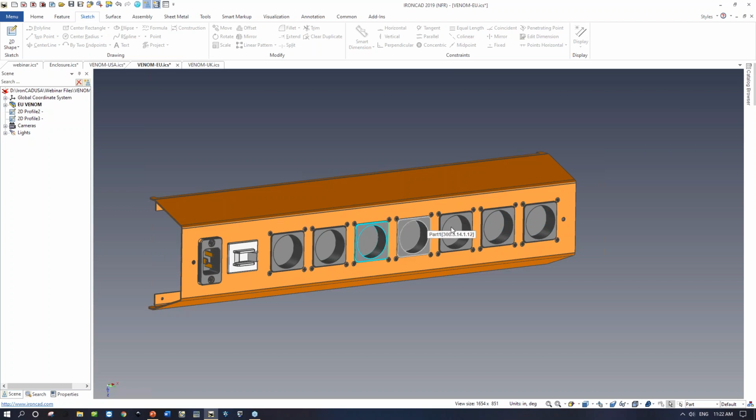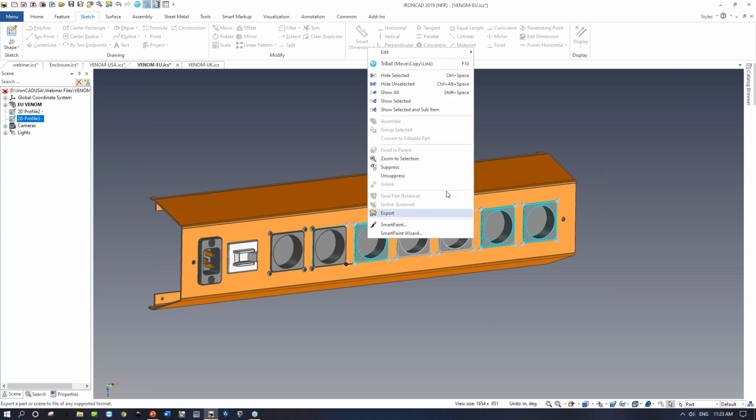Hey, RJ, do you know a simple way to do this, or am I doing it the right way? Would you do it just like this? He might be on mute. You can use box select. Really? Just on those parts? Yeah. I don't want the outside parts, though. You can use the box select down there on the bottom right. Next to the part selector down at the bottom, there's a box select command. Just use that. Oh, really? Ah, and then I could use Shift Select to get rid of what I don't want, right? You know what? I don't even need to do that. I like what you just did. Thank you for that. Okay, that was really cool.